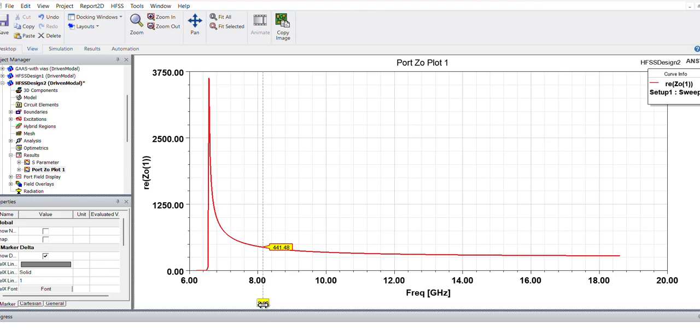You can see the rate of growth here, the tan theta of this one, is much higher than this section, if you think of it as a piecewise linear section. There is a huge variation of impedance from 6.557 gigahertz to 8.2 gigahertz, and after that it settles down a little bit. In this zone, say, from 850 ohm it is going to 450, so half.